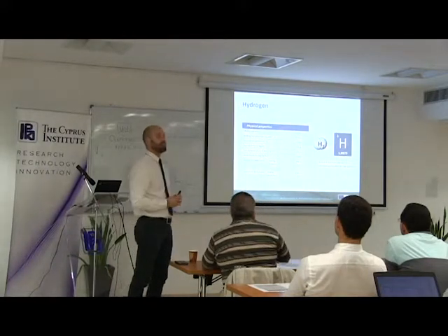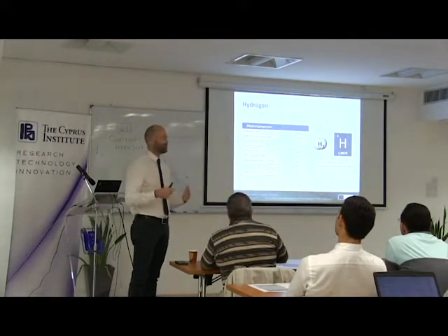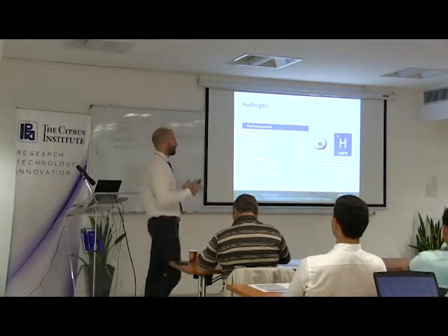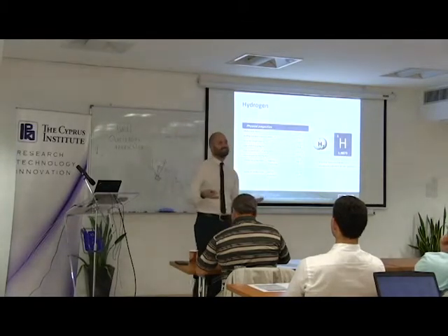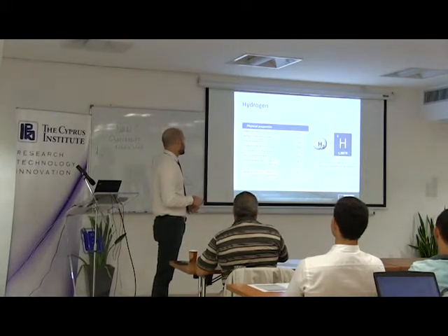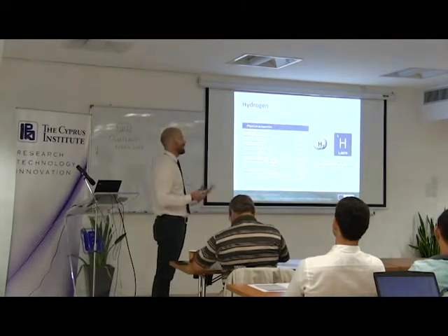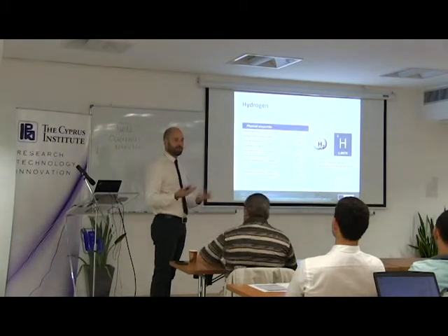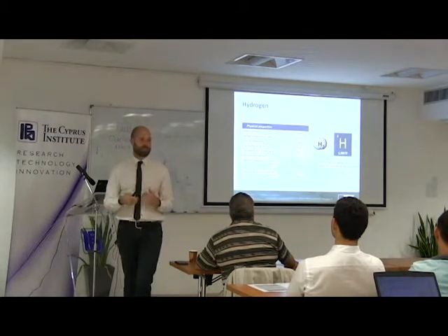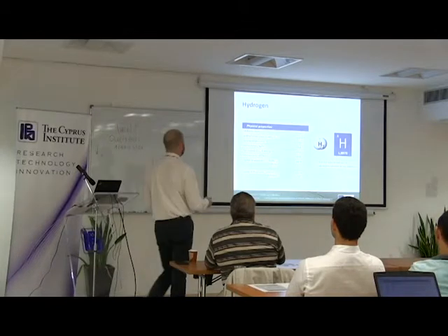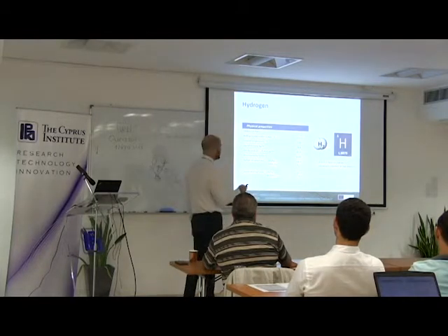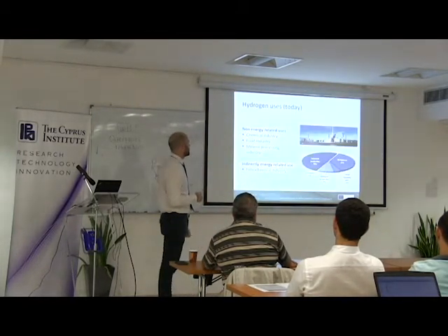Because either you compress the hydrogen very much, since it's so light, in order to store a significant amount of hydrogen you need very high pressures. Or, if you want to store significant amounts, you can go to the liquid phase, which is the usual approach with other components, but in this case, to go to the liquid phase, you definitely need cryogenic transport. You need to go to a very low temperature. On the other hand, the heating value is interesting, and we will see it possesses other very interesting properties.